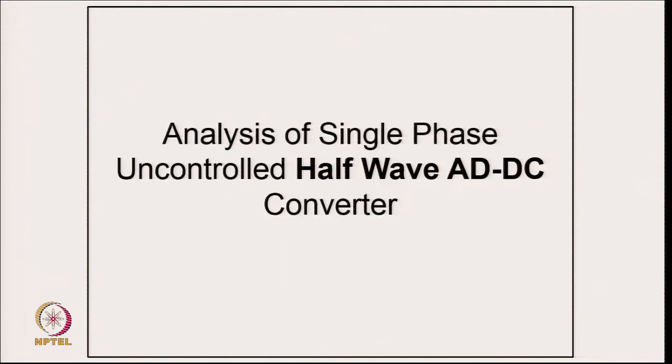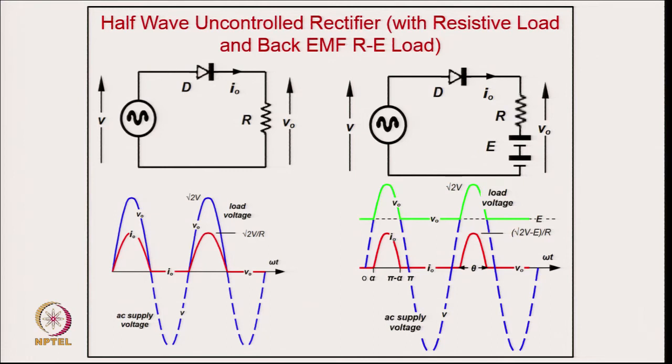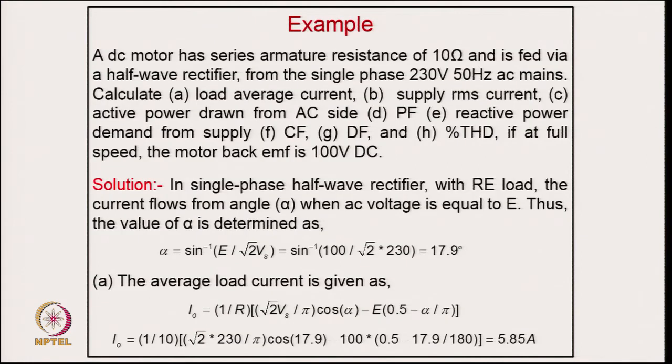Coming to the half wave rectifier, you get current only in the positive half cycle, where the voltage is positive, and you can see that you are injecting a DC component into the supply system. Because of this, it is used only for very low power battery charging. You are not only injecting harmonics, but virtually even the DC component into the supply system, which may even saturate the transformer of the supply system.